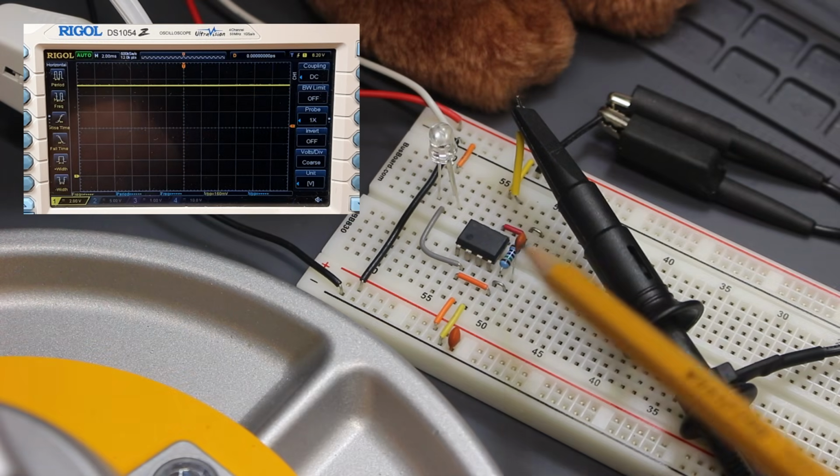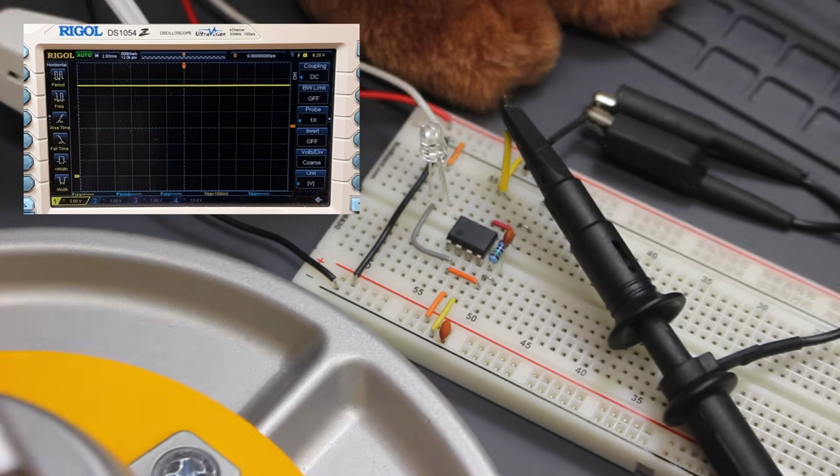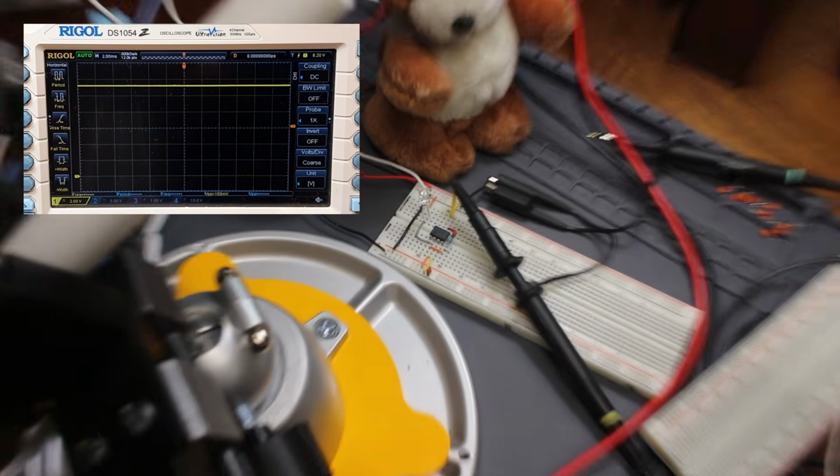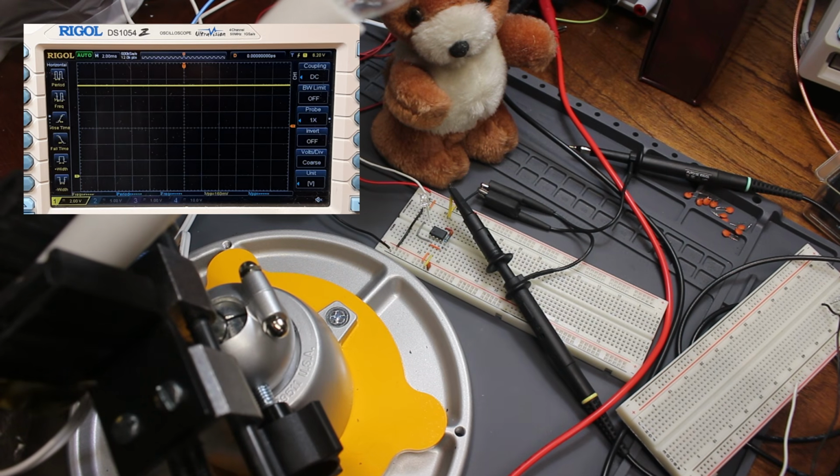Here's the circuit on the breadboard. It's not much to look at since there's only a handful of components. There's a bit of a mess surrounding it because there are multiple light sources that I want to experiment with. With both the room lights and the desk lamp lit, the output is totally saturated. I'd need to use a smaller feedback resistor to handle this much light.